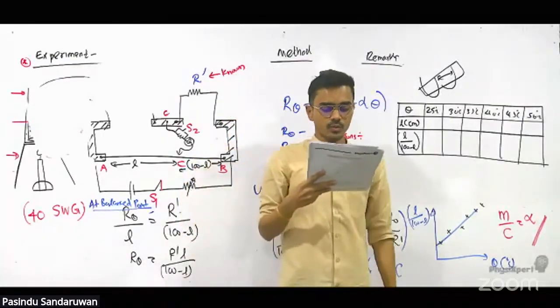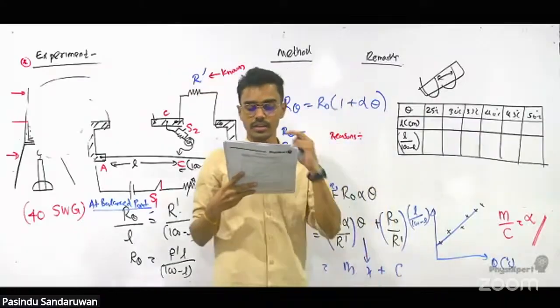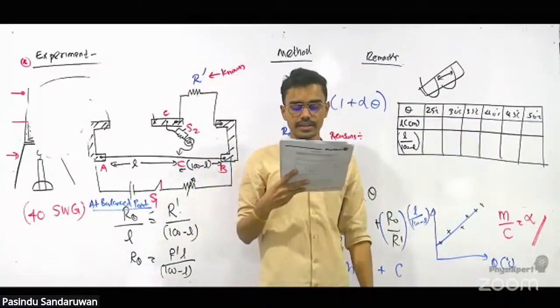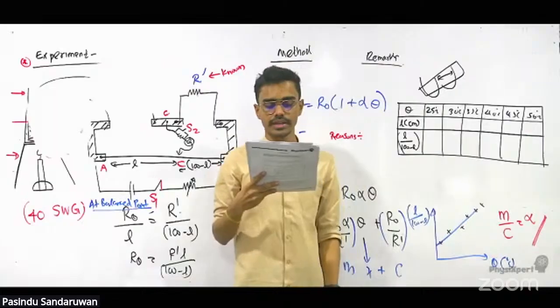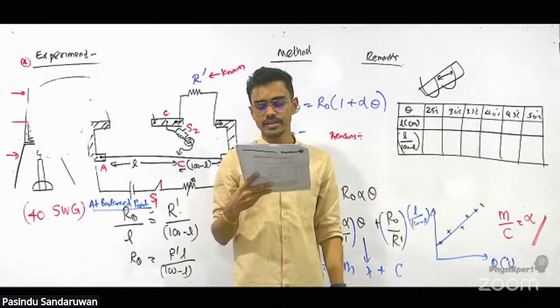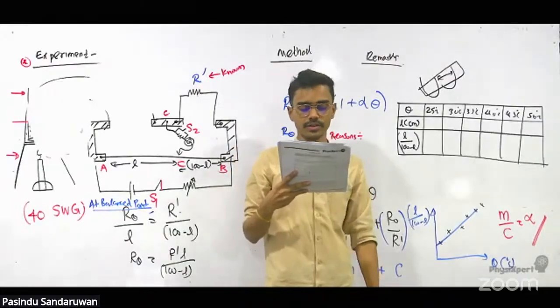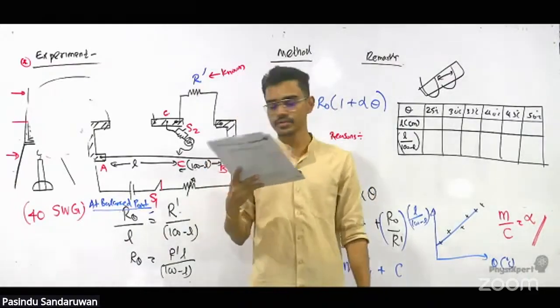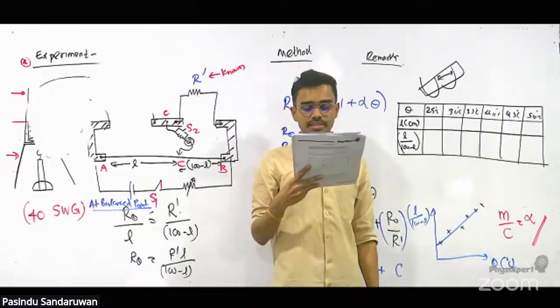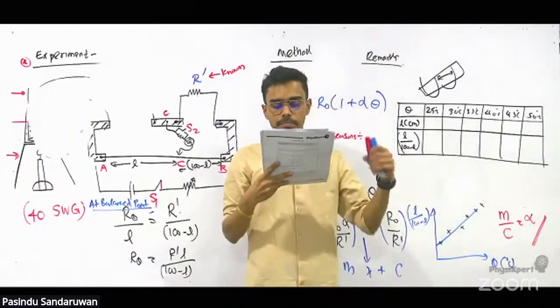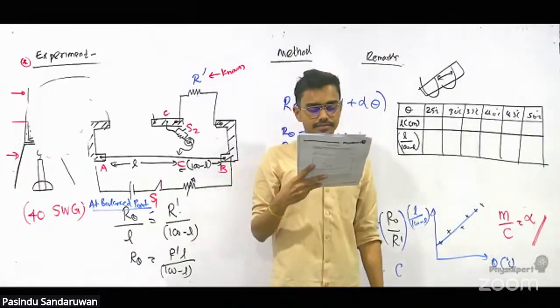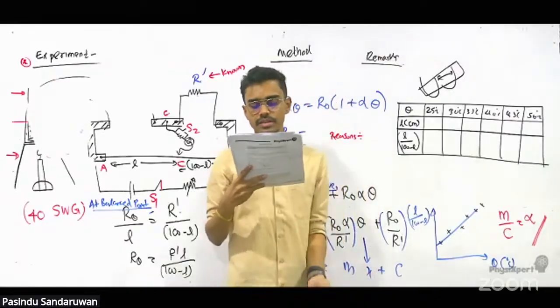When preparing the coil of wire, take a cylindrical piece of wood about 10 centimeters in length and about 2.5 centimeters in diameter, and insulated copper wire of 40 SWG, about 5 meters in length. Bend the wire into a double thread and wrap it around the piece of wood as shown in the figure.